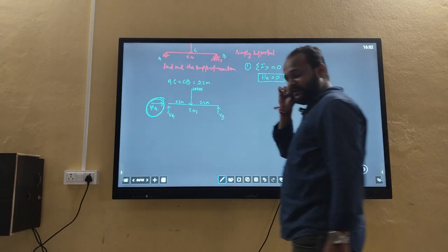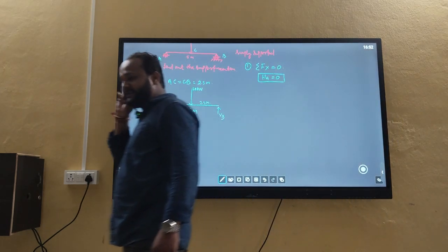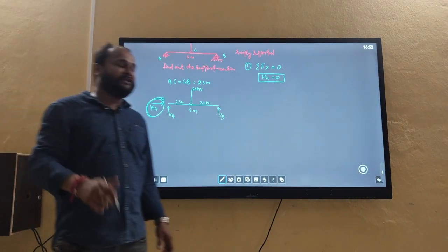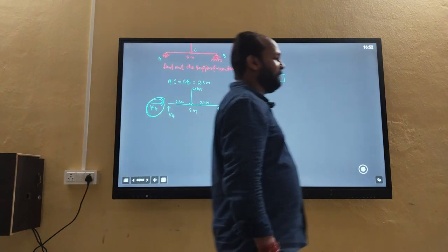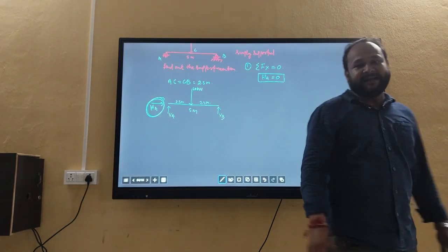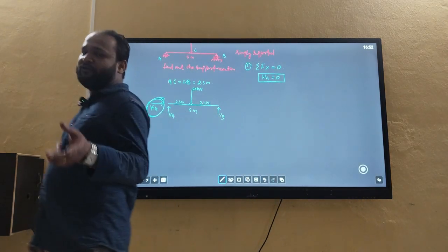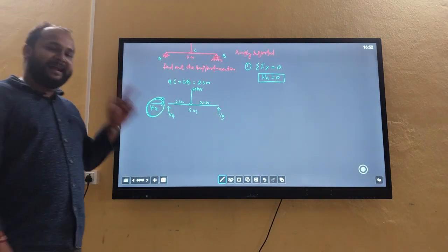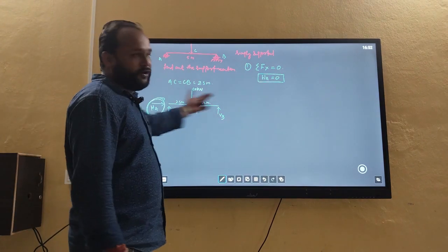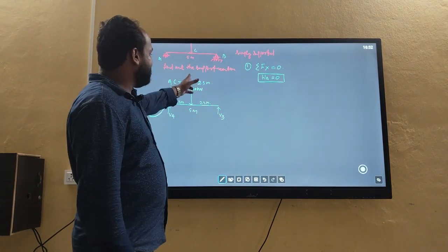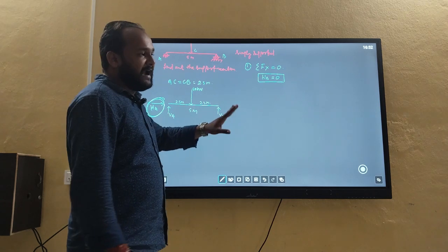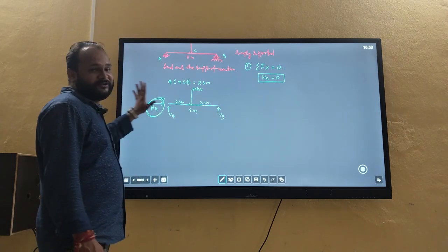When the load is applied to a beam at an angle, then the cos component and sine component will be resolved. At that time only you will get the horizontal reaction. If the load is acting perpendicularly to the plane, at that time no horizontal reactions will be generated.